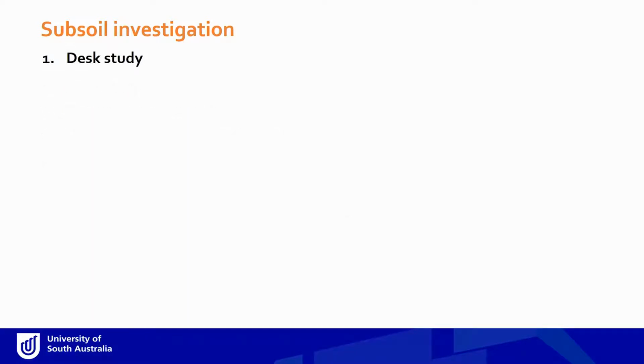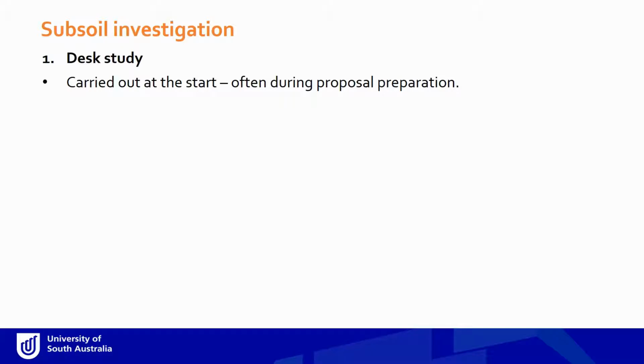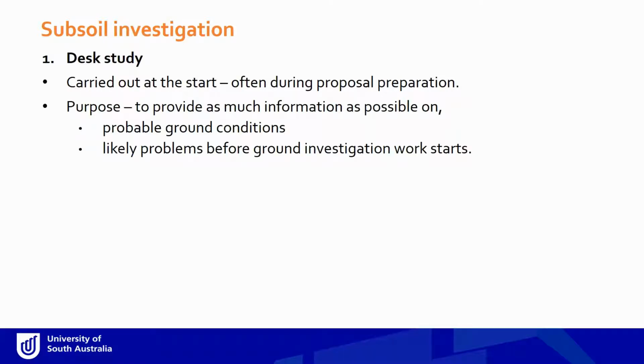Let's start with a desk study. As the name suggests, we sit on a desk and basically study. The main purpose of this is to gather as much information as we can before we actually start doing the actual exploration. This desk study is often done during the proposal preparation stage, and what we're targeting to find is the probable ground condition. Is it going to be a silty soil or sandy soil or clay soil or whatever?